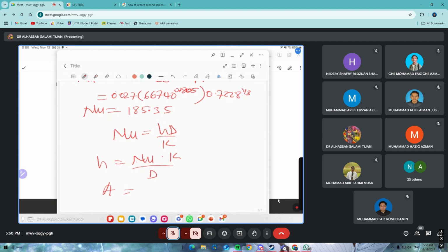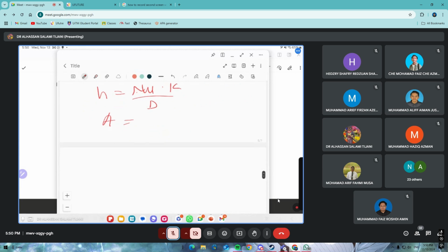Calculate h first. h equals the Nusselt number times 0.02735 times 185.53, all divided by 0.15.